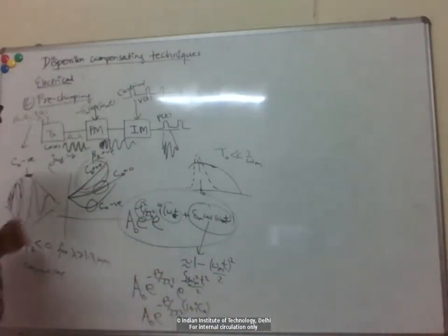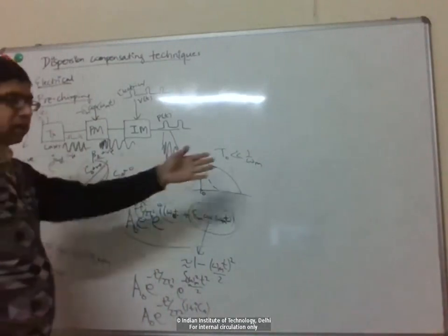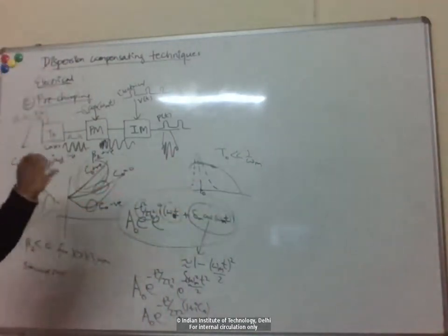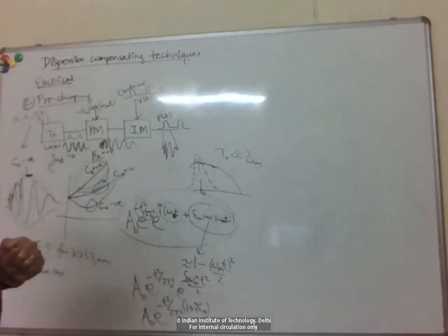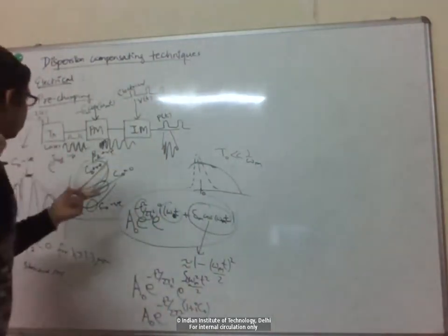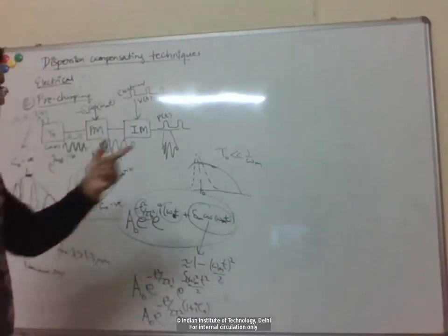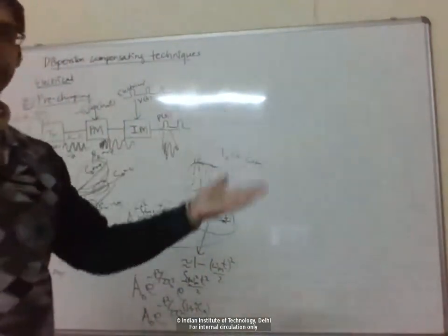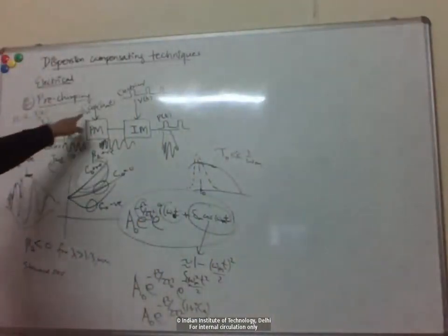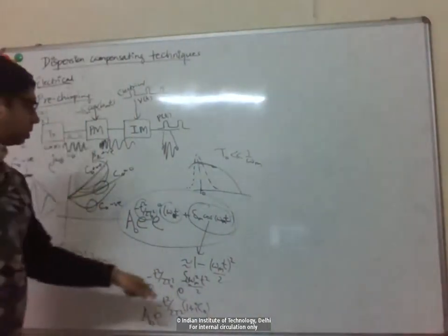By knowing this broadening, we derive analytical results for how much the pulse broadens, depending on the initial chirp and the fiber GVD parameters, etc. So we can calculate the optimum input chirp that leads to the smallest pulse width at the receiver and hence the maximum bit rate. Then you can choose delta m and omega m appropriately to impart that.